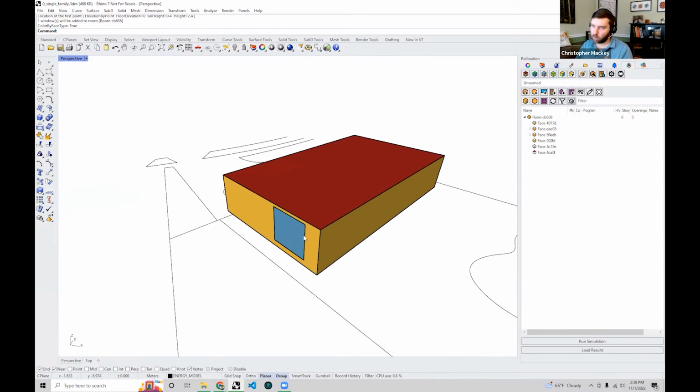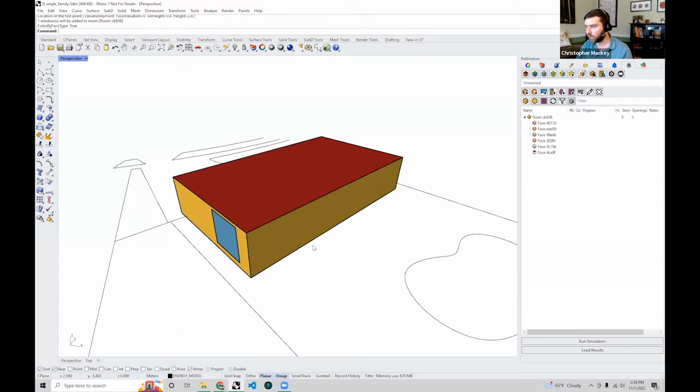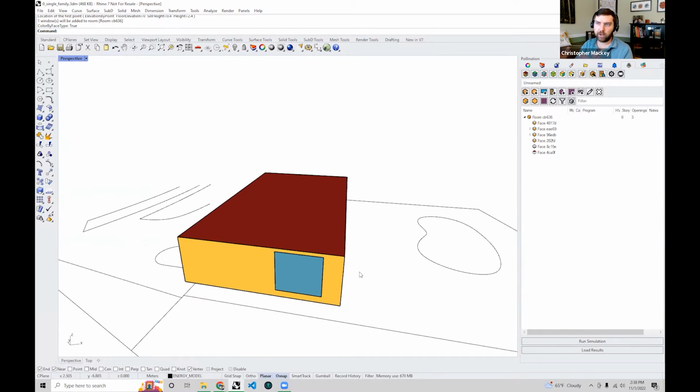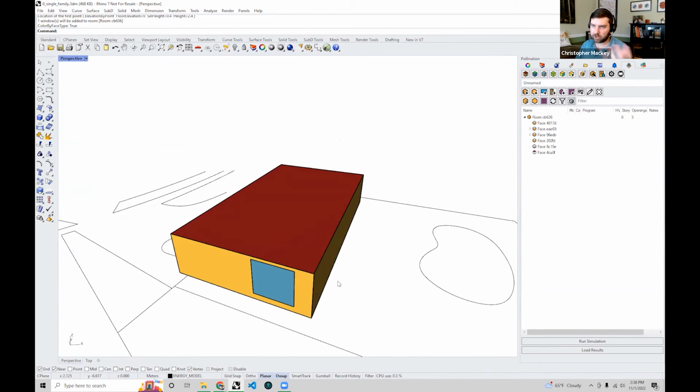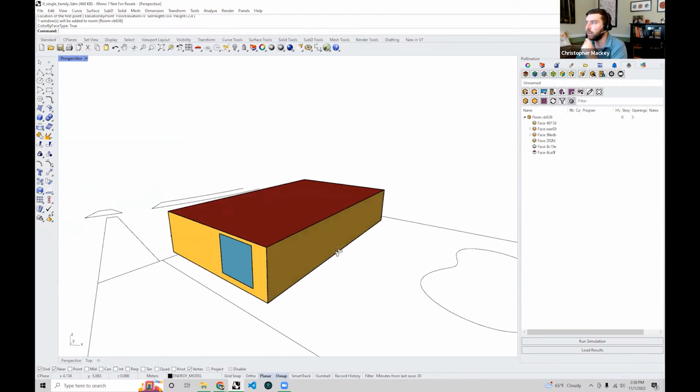So this floor plan way is definitely one way of drawing apertures very quickly. You can easily trace over all your room geometries and trace over the window sills like this. Sometimes though, if you have a much more detailed facade with different shapes of windows all over it, maybe simply tracing from the plan may not really cut it.